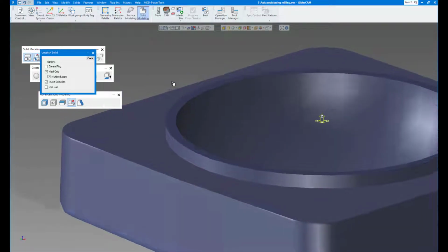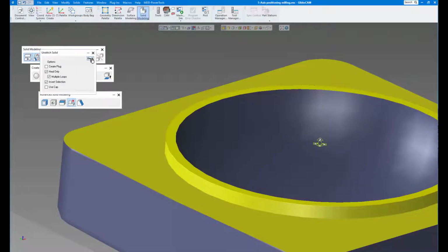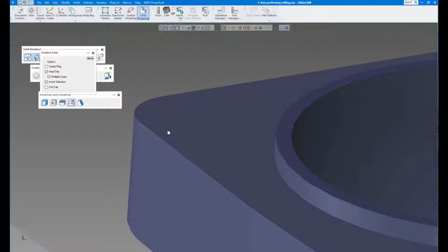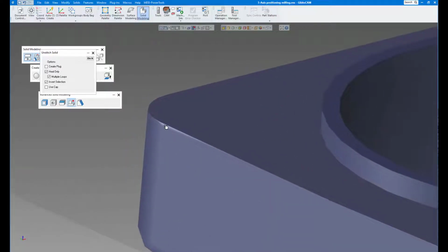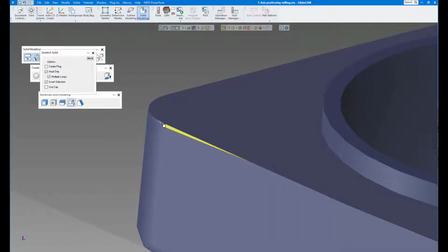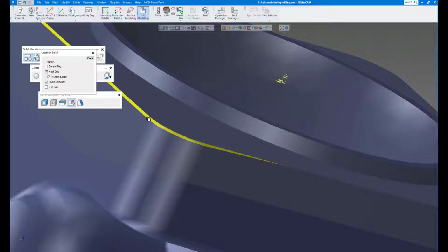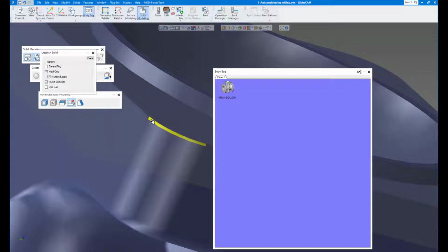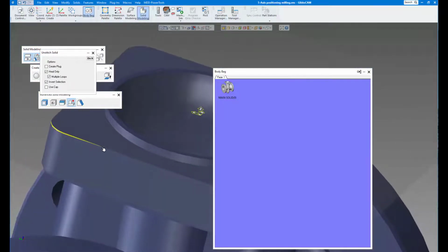That healed up nicely. I'm going to select here and here and here, and I believe this will fail, as you can see, because notice there's a little taper right here. Since this is a casting, it has to have taper to come out of the mold. So I'm going to click on that. And I don't believe it goes past there. Whoops. So let's do that again. Okay. Heal up that, and that goes to a sliver there.